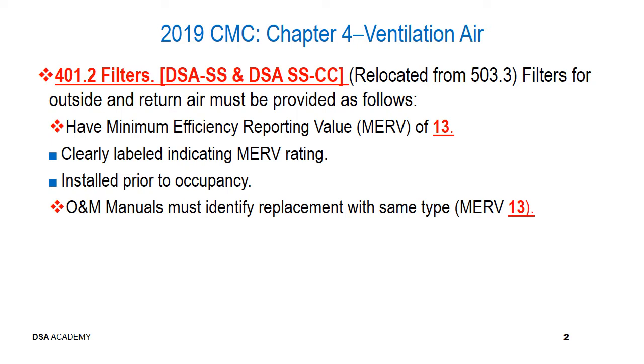These filters have got to be clearly labeled, indicating their MERV rating. New filters of the compliant MERV rating of 13 are required to be installed prior to occupancy. And the O&M Manuals have to also identify that replacement of the filters must comply with a MERV 13 rating.